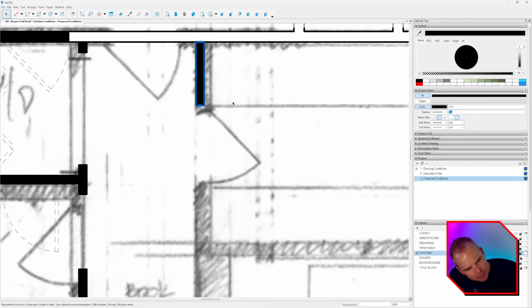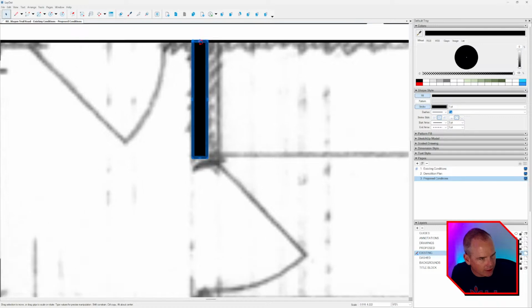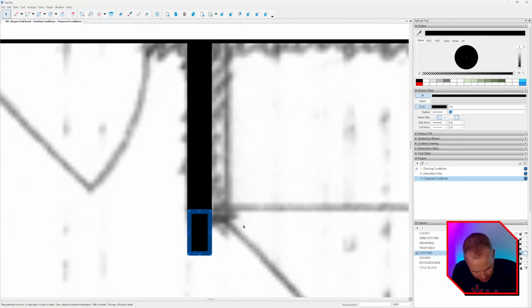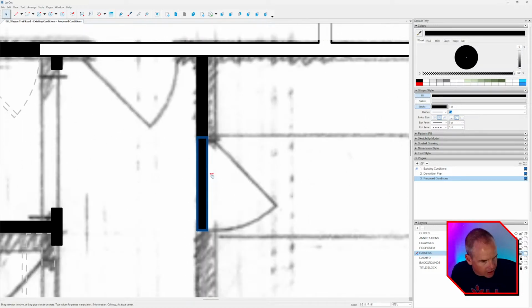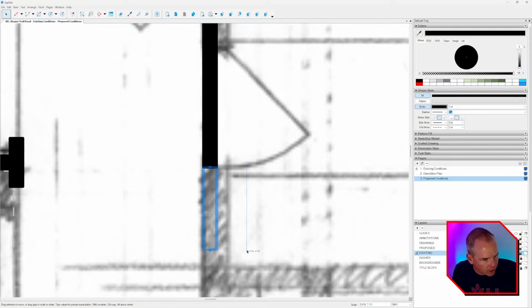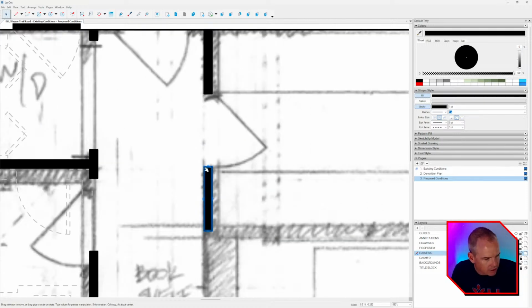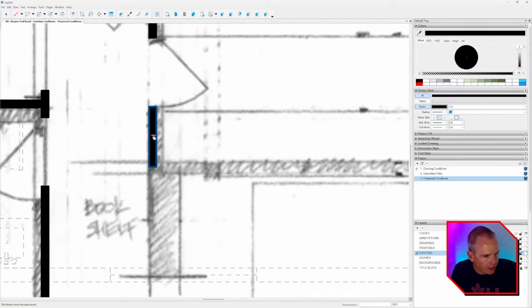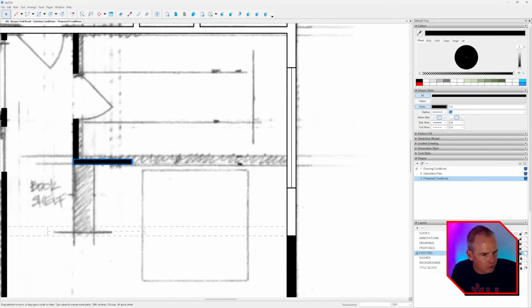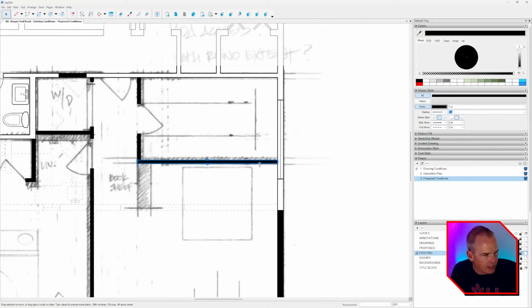I'm gonna call it 28 inches, and then we're gonna make a copy of this at minus 32 inches like that, and then fold it inside out at minus 28 inches like that. And then we can move our precise move grip and rotate 90, and this one stretches all the way to the end.